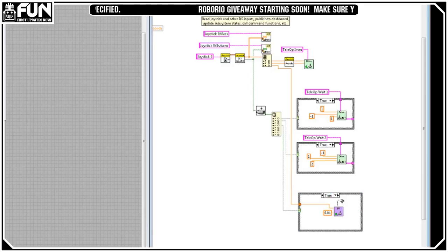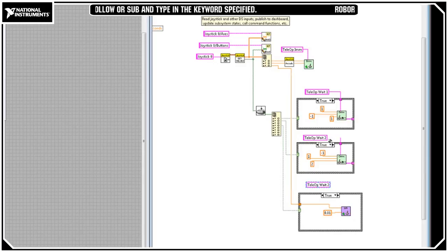We can go ahead and give this a description. Go ahead and give it a name. So I'll drag this over here. This can go in or out of the case structure here. I'm just going to copy this by Control-clicking on it and then dragging. So I can rename this to forklift lift so that I know what command is executing here.